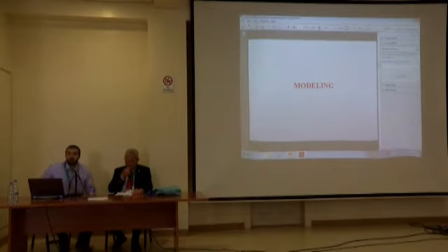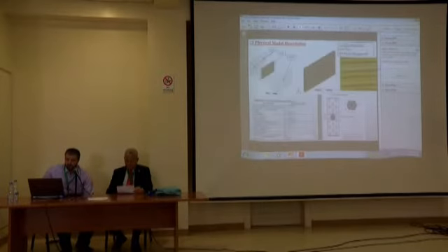Now I will start presenting the modeling procedure of the application that we have done. First of all, this is our physical model. It's just a coil placed inside this box, where air enters from the two inlets, hits the coil, exchanges heat and leaves through the outlet. Our coil here is made up of 600 fins and 84 pipes arranged in a staggered manner, and the table below and the figure also show some geometric specifications we're not interested in.